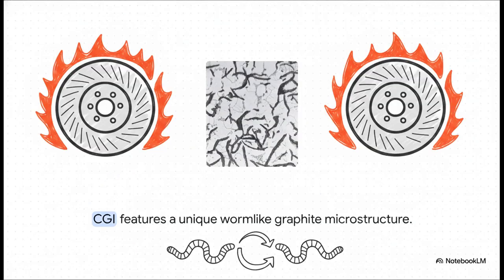It's brilliant. And the control we have over microstructure doesn't even stop there. By very carefully balancing the silicon, magnesium, and other additives, modern metallurgists have developed something called compacted graphite iron, or CGI. The graphite here takes on a really unique worm-like shape. It's sort of an intermediate form, sitting between the flakes and the spheres. This specific vermicular microstructure provides amazing thermal conductivity and resistance to thermal shock. It's the absolute ideal material choice when you need something to handle rapid, extreme temperature changes without fracturing, which, as it turns out, is exactly why it's heavily used for the brake discs on high-speed trains.